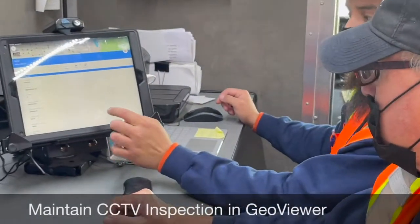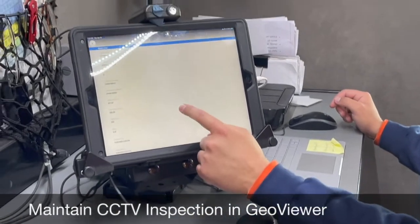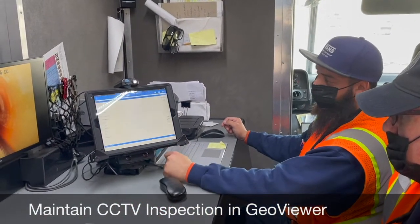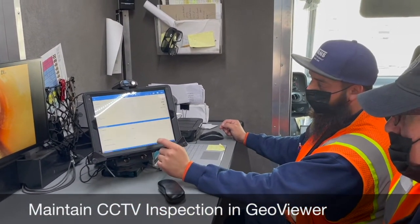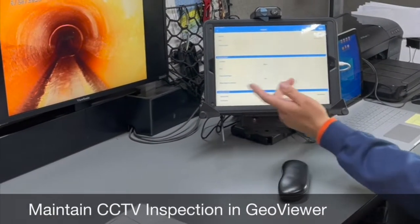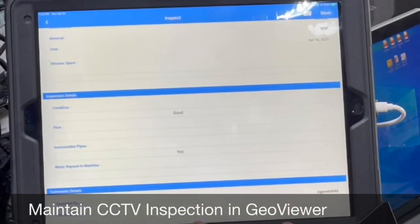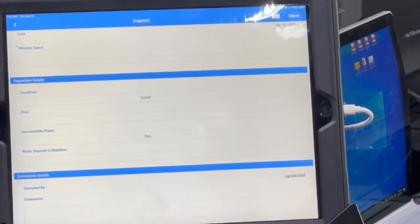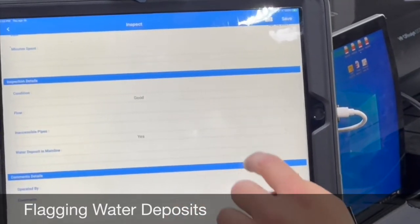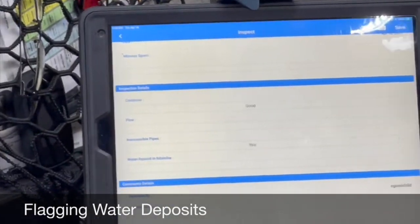And when we go to inspect, it gives you all our upstream, our downstreams, the length of our pipe, the size of our pipe and the material it's made from. And click inspection, it'll give you all the data on it, the time, the date, location, and if we're going with flow, we put down what the condition is, if it's an accessible or inaccessible pipe, and if we find water deposits, then we'll flag it, and further on down the line, we'll clear the water deposits with sewer cleaning trucks.